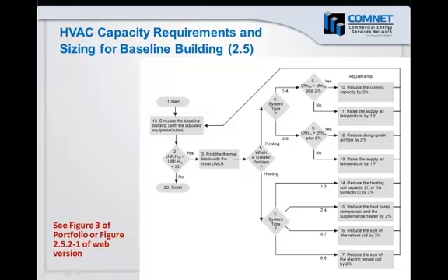The next section in Chapter 2, Section 2.5, addresses how HVAC systems are sized. Any size adjustments to the rated building or the proposed design have to be made by the engineer or by the energy modeler, and these should agree with the contract documents, so that if the size of equipment is reduced or increased in the model, the construction documents should reflect this.